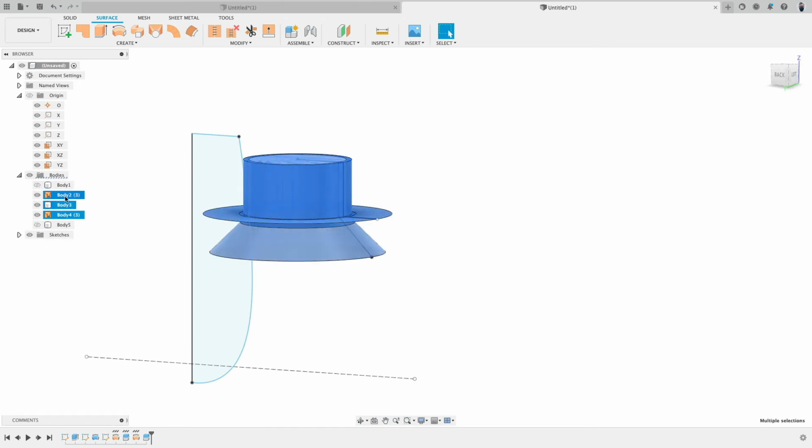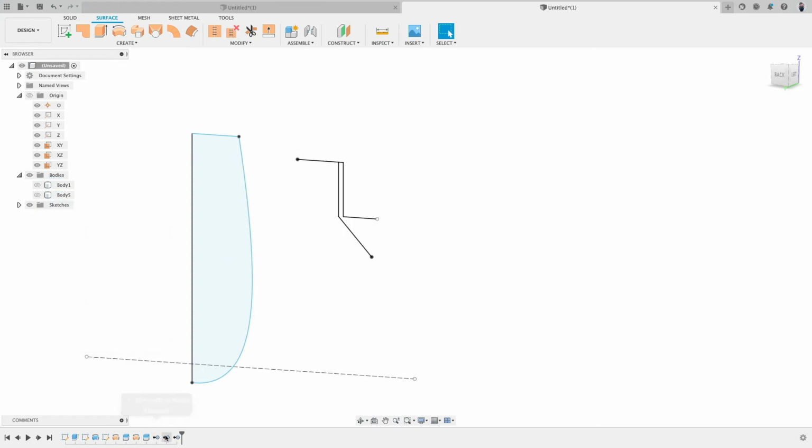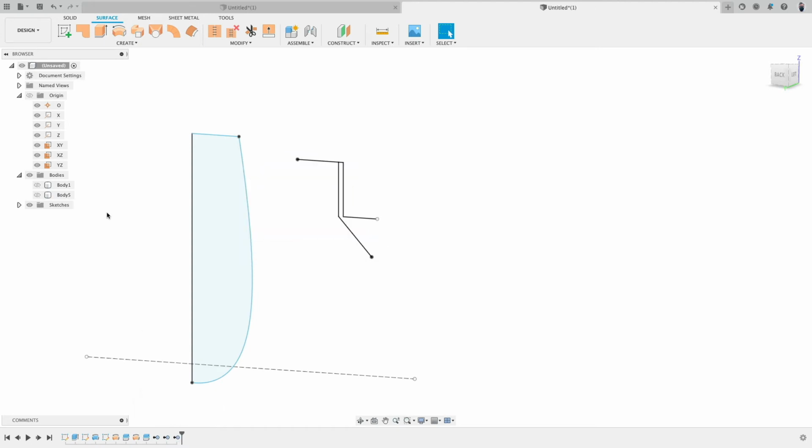In the browser, select all three, right click, do not click delete. The moment we click delete, we really delete it out of the scene. And from the beginning, it's gone. Gone, gone, gone, gone. Doesn't come back. We want, honestly, just to remove it right now out of our timeline. So I remove. You see here, there's like 3 remove features. When we go back, look, they're back there. No? Hopefully that makes sense. Again, remove is temporarily in the timeline, remove it. When I delete, it's really out of my file. It is gone.